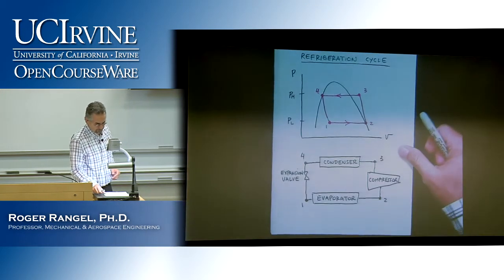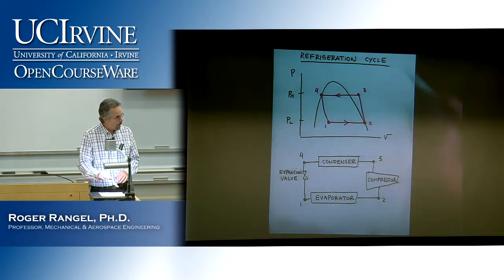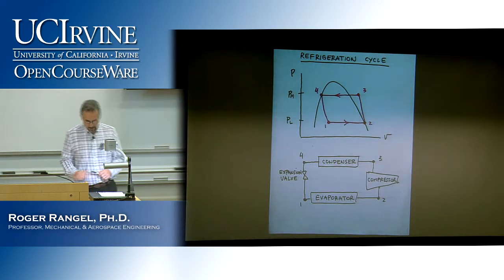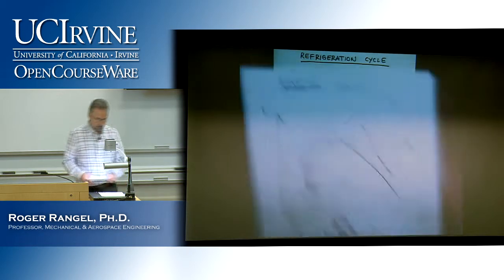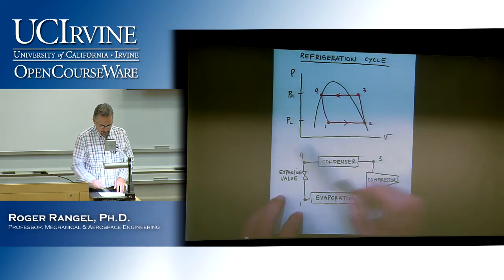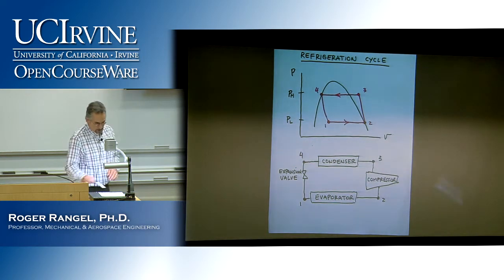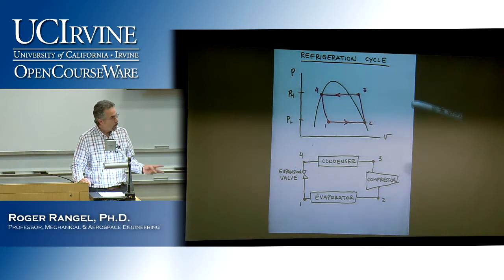The last one is, in my list, the refrigeration cycle. First thing to notice is that it runs the other way. So usually when you sketch the power cycles, they go clockwise on these diagrams. Now here's a refrigeration cycle, also in a PV diagram. It goes the other way. But again, it's still between 2 isobars and 2 adiabatic lines.